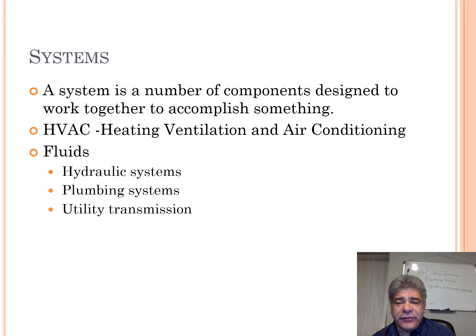My system is slightly different, as I have a geothermal system, but I'll explain how it works. I have a tank that is storing hot water when it's in heating mode, bringing the water up from underground and heating it up to about 115 degrees. When my system calls for heat, that water runs through a set of coils, and a fan blows over that and pushes the hot air through a series of ducts into the house. And there the house is heated. The thing with a system is that it has to be designed to work together, because if one part of it fails, the whole system could fail, right?